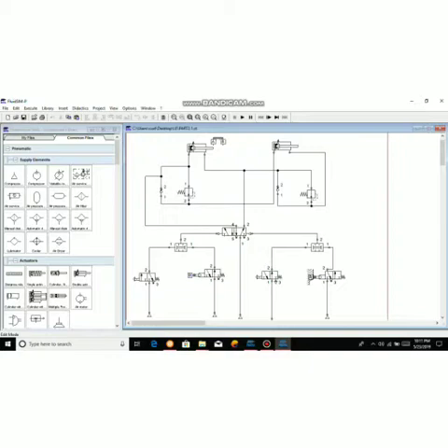The two double acting cylinders use air force to move both sides, where they have two ports, for outflow and inflow. Meanwhile, the 5/2 impulse valve is linked between the double acting cylinders, and it moves forward and backward to control flow.